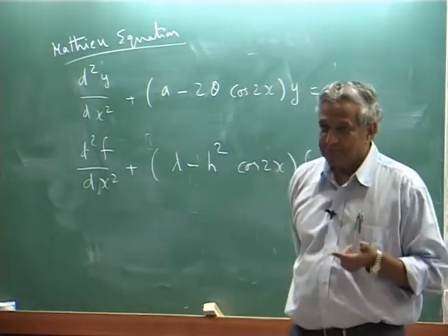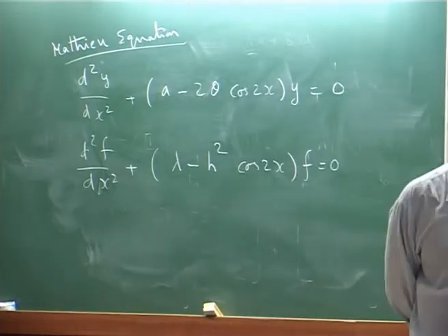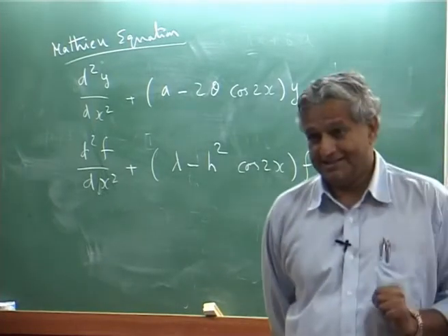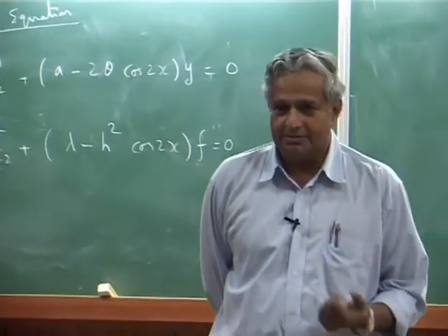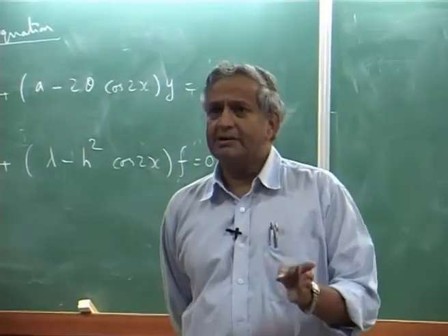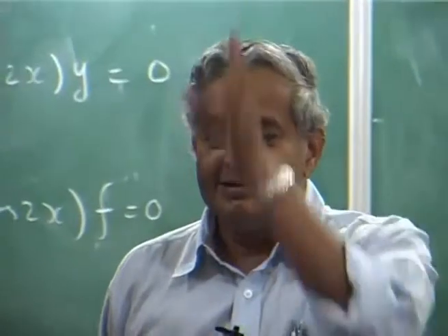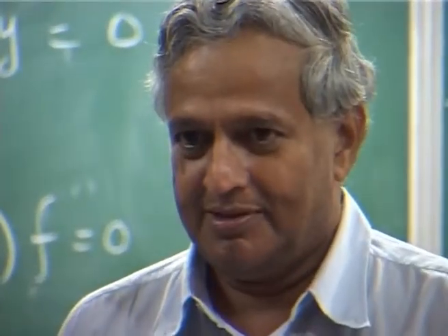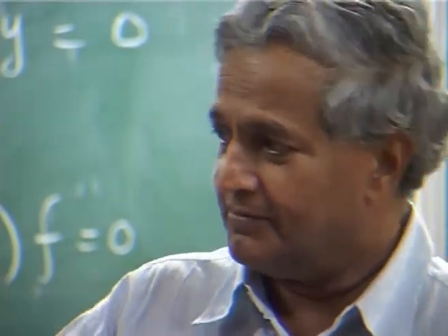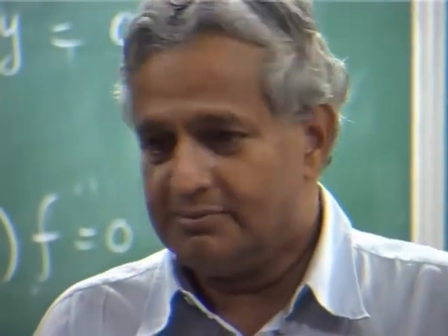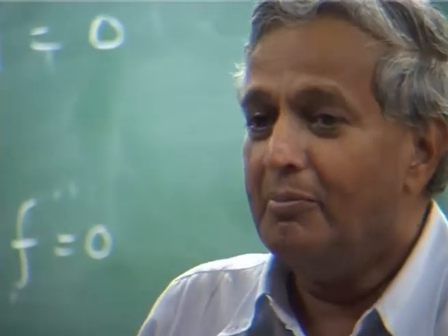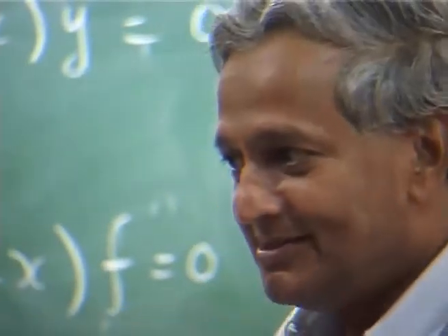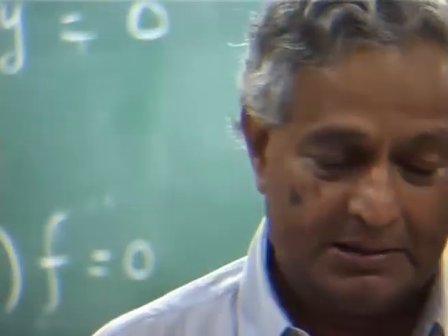But it will not tell you what is the value of damping. You can only say it is stable, it is unstable. Now you may ask how stable it is, am I near the imaginary axis, how close I am. If you are very far on either side you are highly stable, but if you are very near, your stability is just marginal, but that result will not give you that. But it will tell you the regions, that is a separate formulation derivation.